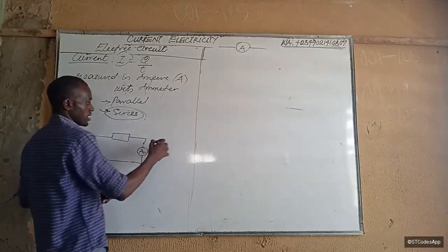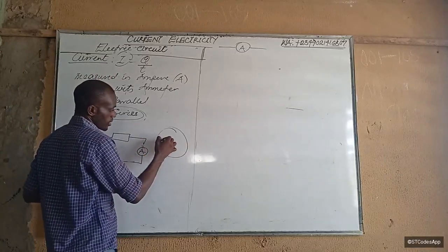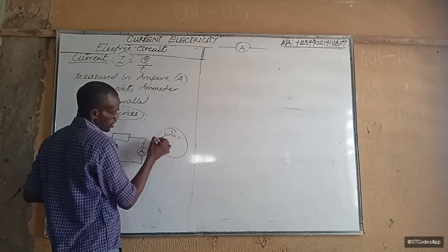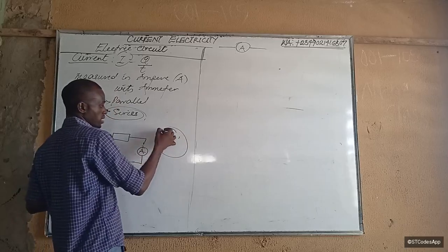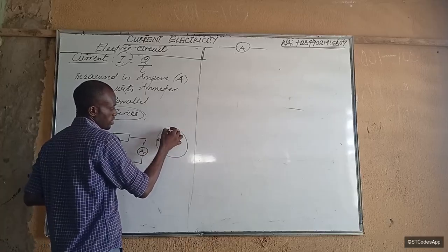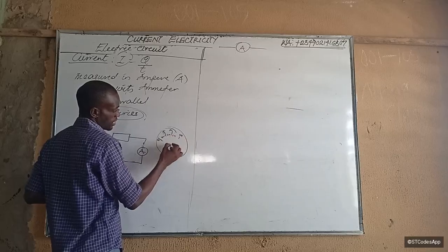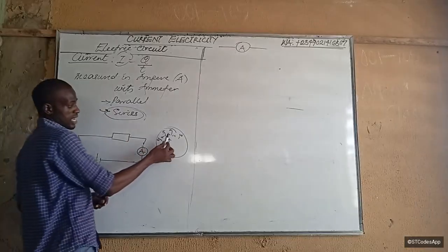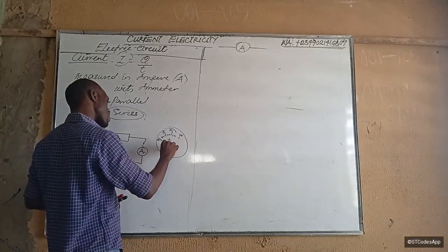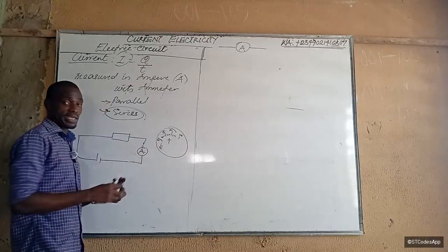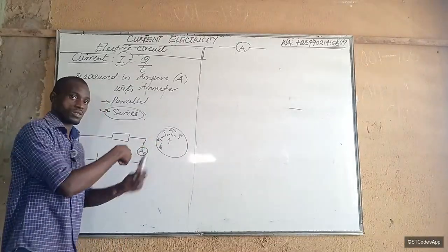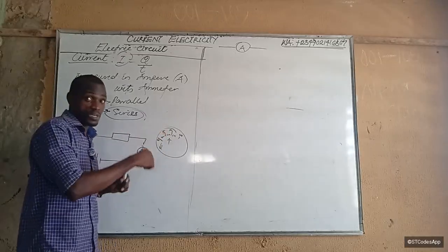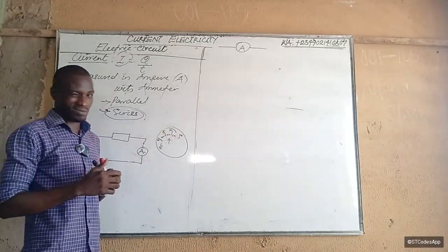But of course, you see that's a dial, okay? It is calibrated. Okay, so this point could be 0 amperes, let's say 5 amperes, 10 amperes, 20 amperes. Let's say the maximum it can measure is 20 amperes. Now, what happens is this: if you connect an ammeter and the ammeter deflects away from the zero mark, you should change the connection because it's supposed to deflect in this direction. So it means you have put the negative into positive and you have misconnected it.